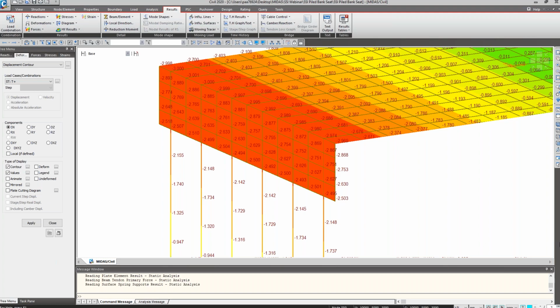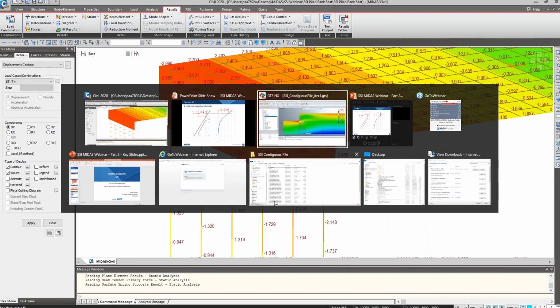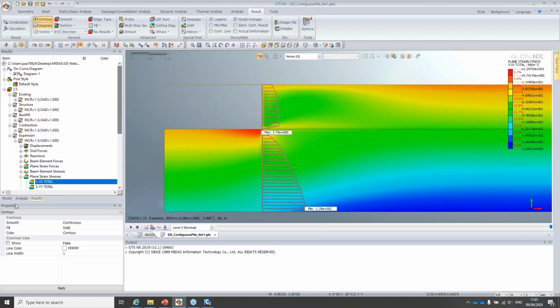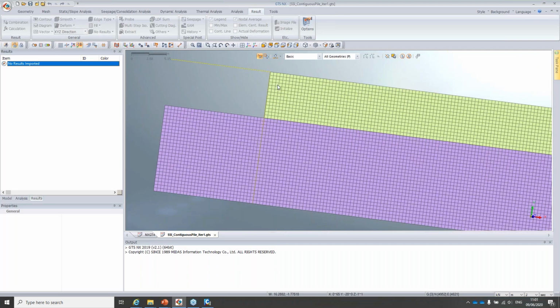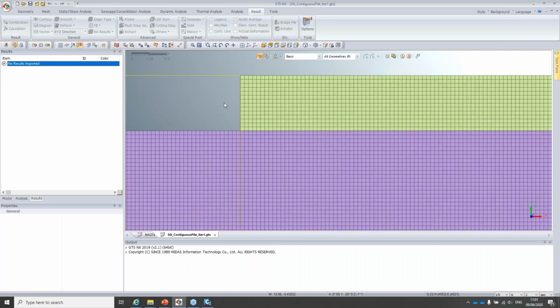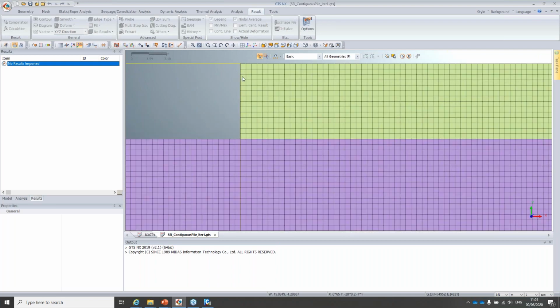Another one is how the software will differentiate between pile and structural elements. How does it not include interaction properties like normal and tangential behavior for the pile embedded in the ground? And that's another very good question, which I wanted to mention. I forgot when I was discussing. On the second example, we have modeled the pile as fully fixed with the ground, and we know that that's not reality. We can expect to see some differential movements between the ground and the pile.